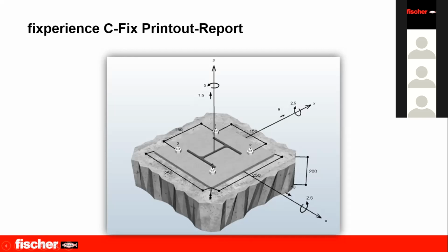We will make a pull-out test on the site. When we make the pull-out test, this value we should compare it with which value exactly, to 1.5 or which value? Actually, the software makes finite element design and finite element analysis, and it distributes these forces to each anchor. These forces, 1.5, 2.5, 2.5, are called the design action.